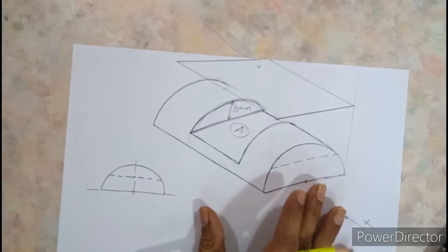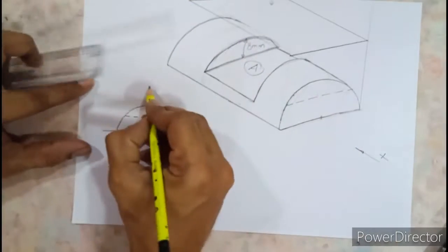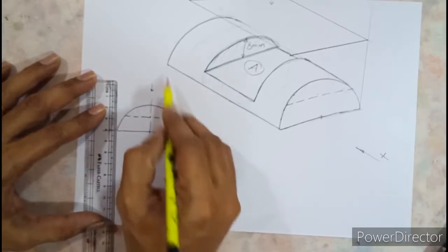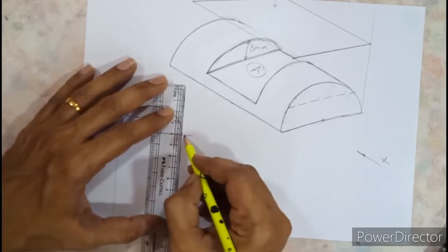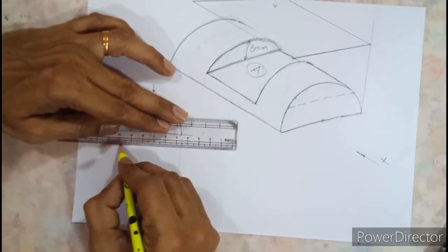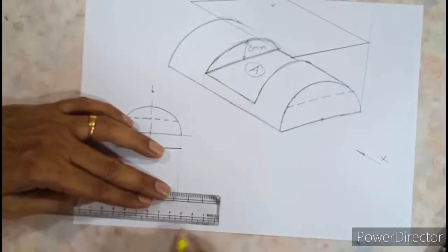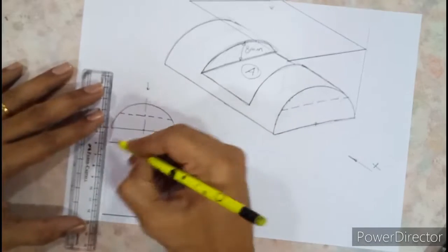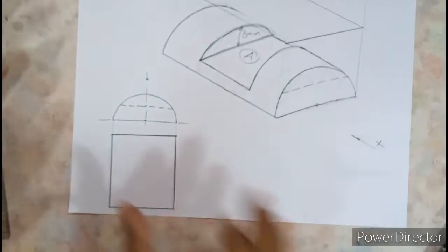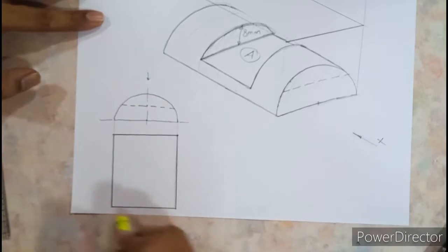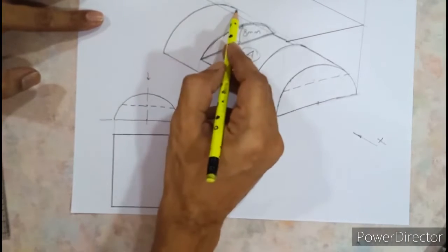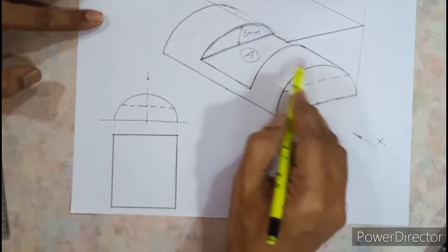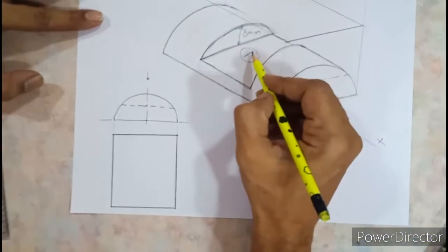Okay, so let us try to visualize and draw the top view. If you look at this diagram from top, and if you project parallel rays of light, because orthographic is all about projecting parallel rays of light, you need to transfer this down and darken this. So that is how we have darkened this one. This is the outer boundary of the semicircle, what can be seen. This outer boundary resembles a semicircular edge, the bottom straight edge, again a semicircular edge, and a straight edge on the other side. Now we need to draw surface A.